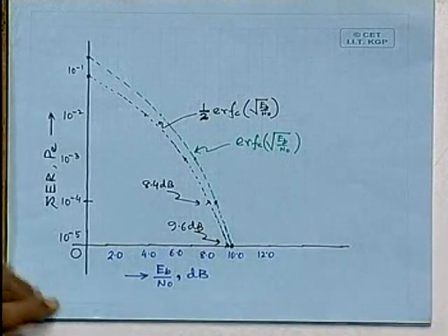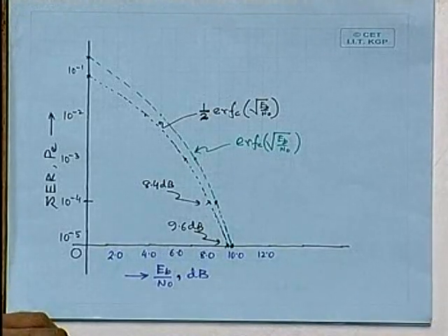Well, his question is till how much amplitude the LNA amplifies. You mean the maximum amplitude? Well, you have read about AGC, automatic gain control, in an earlier course. The AGC normally applies on the IF stage, but sometimes it also applies on the RF stage,